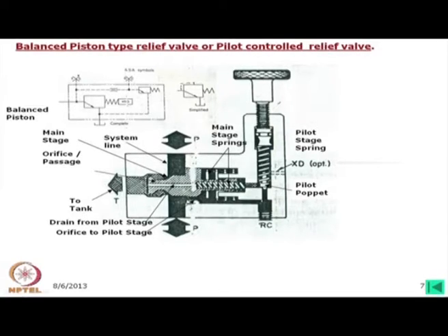But the thing is that this now works on a differential pressure. That means the reduction of pressure here is not very high, or in other words the pressure here and the pressure on this side have a small difference. With that difference, this piston remains at its position for much longer than in the direct acting valve.